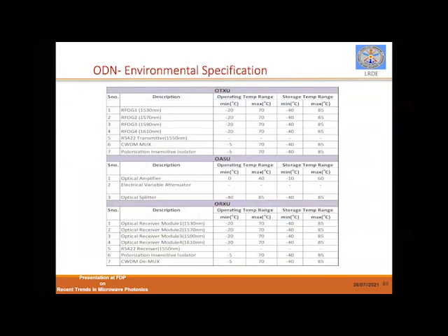And one last point, before I end my talk: when you are trying to design a system with photonics, especially for a defense application, you should always make sure that each of the components used in the system is proof environmentally and from the electromagnetic perspective. When we tried to realize this, we found that except for the optical amplifier, all were having a very good operating temperature range. Only in the case of the amplifier, it was of lesser operating range.